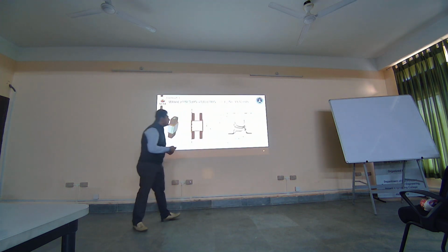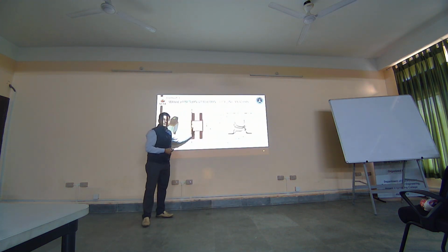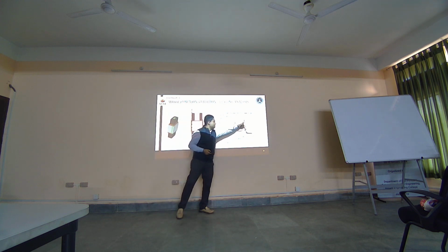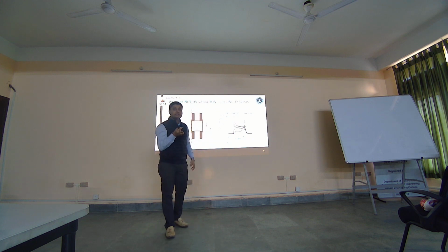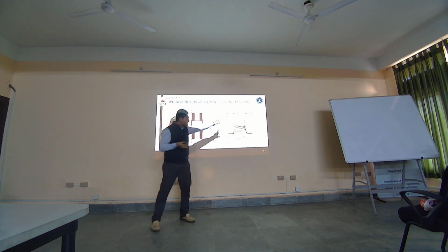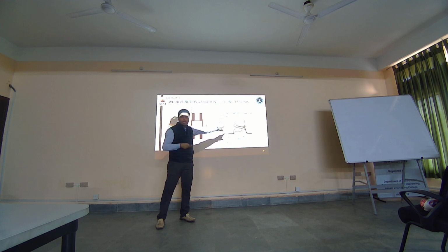And when you move towards the surface, which we call the surface near the gate, then you will have the influence of the adjacent gates which are present, and you will have steeper, you can say pointed, electric fields both towards the source and the gate. Because you are closer towards the gate, the influence of the gate is more. So you can see this kind of a plot.